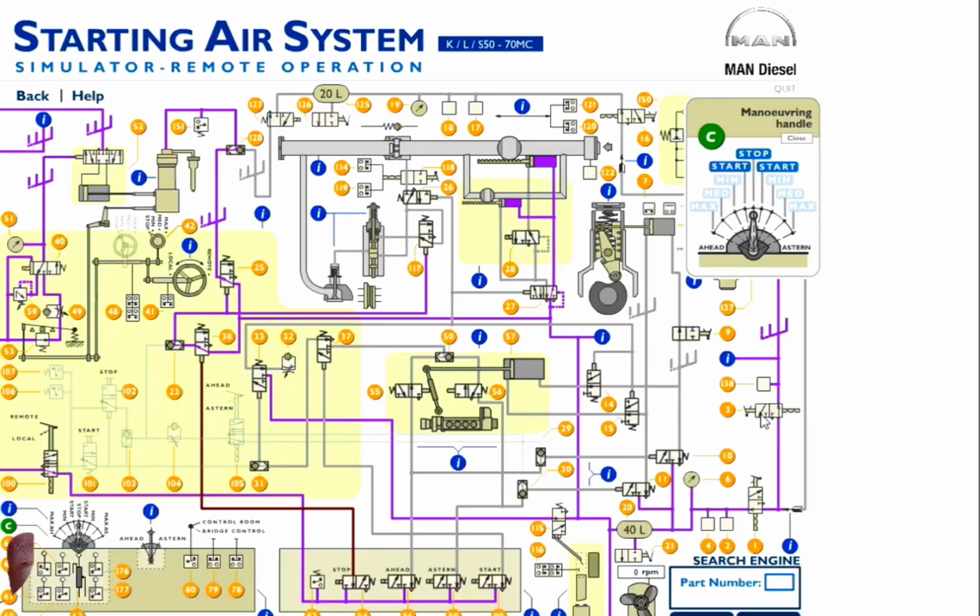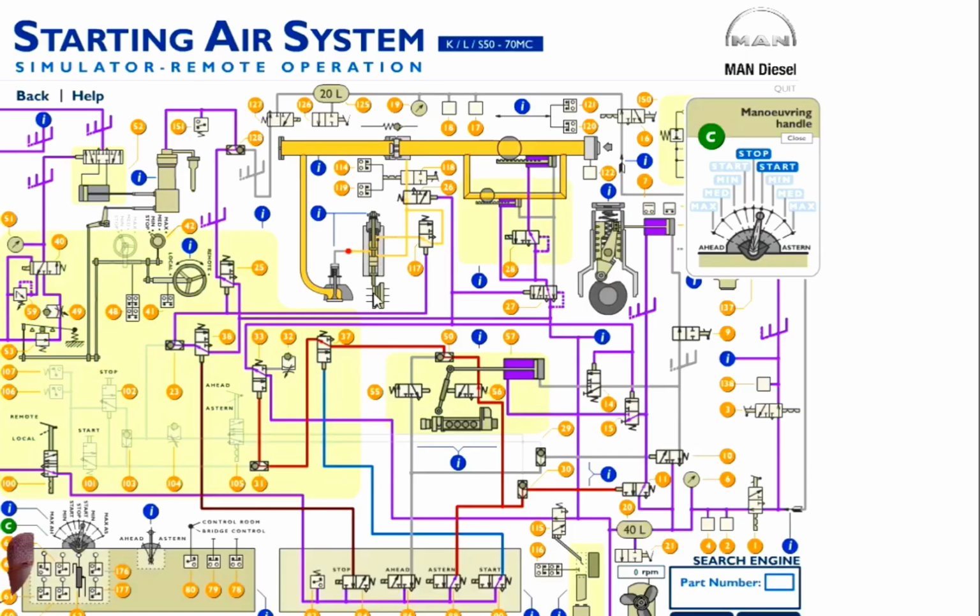And now let's see the opposite direction to astern. Let's see, the signal will flow from here, from astern. Let's see it. Okay, activates to astern position. Okay, change direction here, air distributor, also reversing mechanism, and start signal, it's go here to this valve. Okay, to starting air distributor, open there, here. You can see all the valves working here, and now we're running on air.